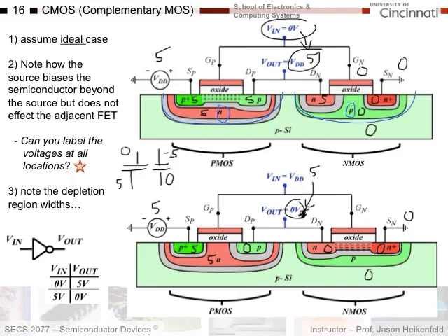Then over here, for the NMOS device, I'll diffuse in my drain and my source. So I'll diffuse in dopant levels to create that. And then over here, I will diffuse in additionally my drain and source with P-type material. And then all I have to do is modulate the channels to be conductive or not for these cases and get the action I can see here.